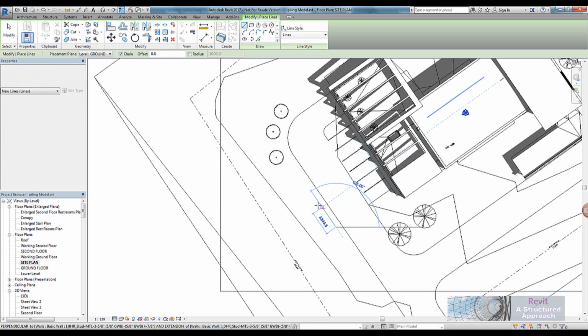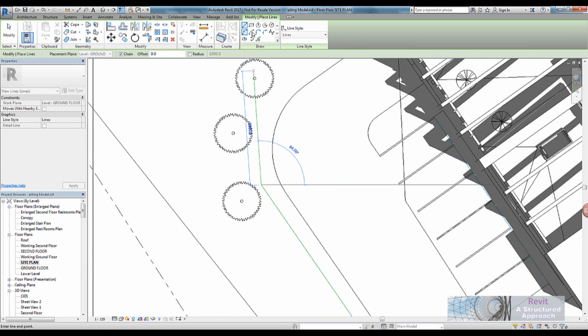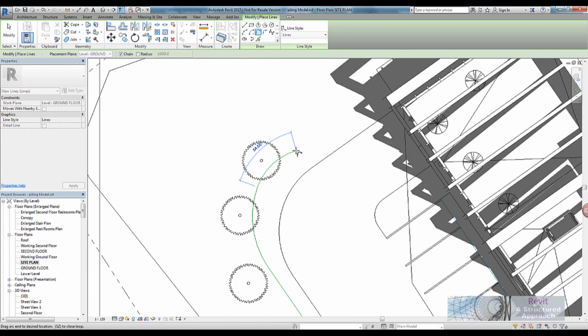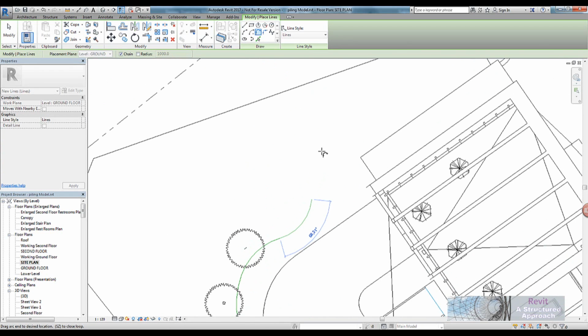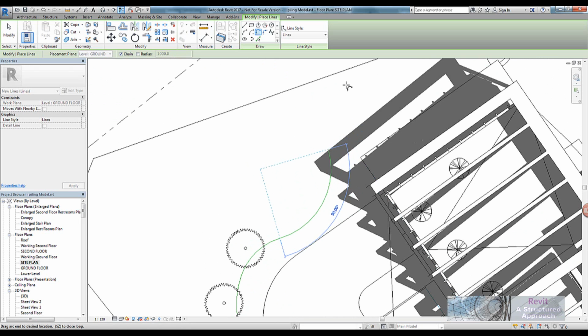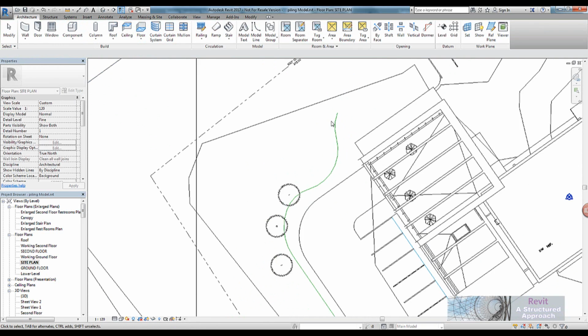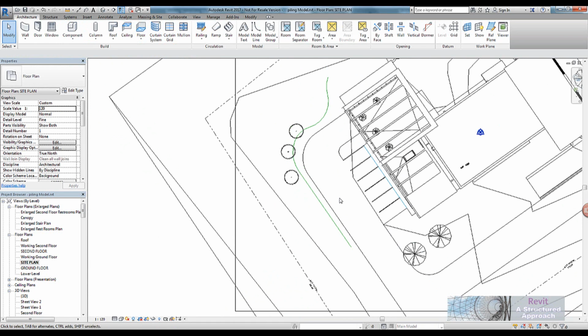So we'll have some sheet piling coming down here. I want to now have a curve starting. So in this example, I'll use a tangent curve here. Perhaps we'll take the curve around over here and then we'll need to retain some earth up this way and just across there. So there's my path that I want to populate with sheet piling.